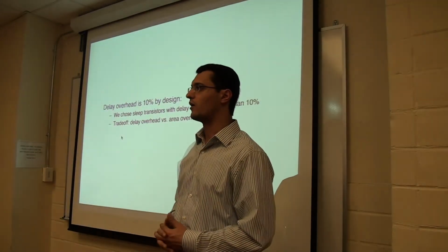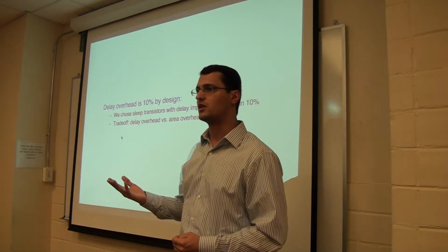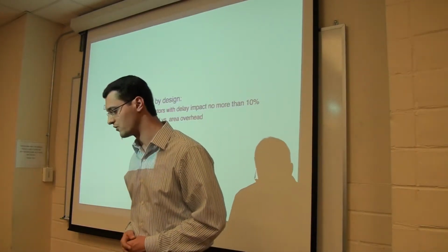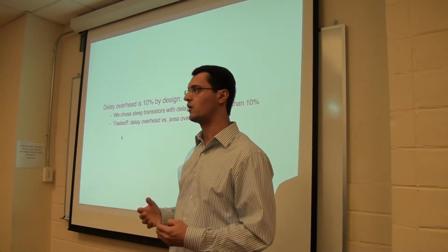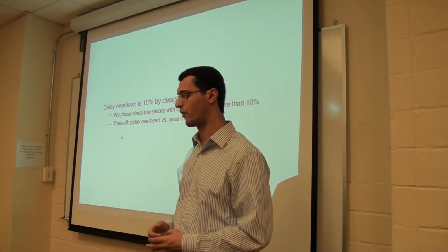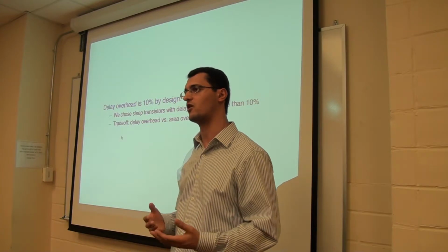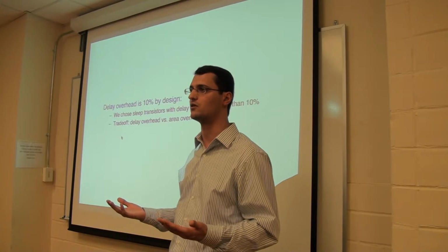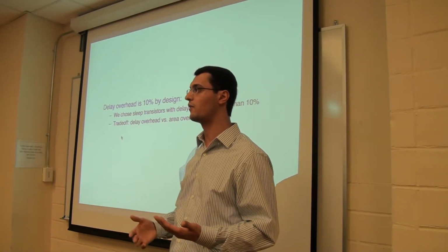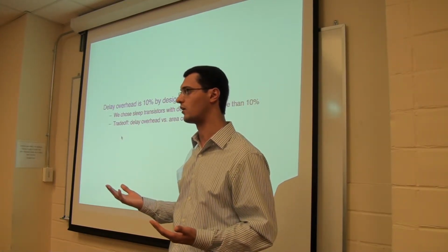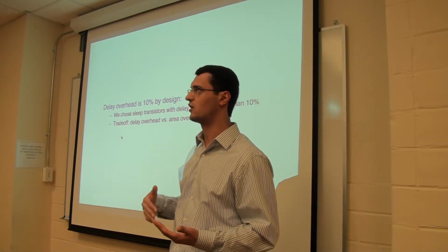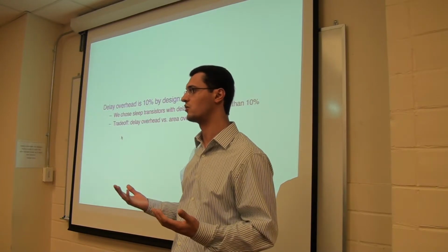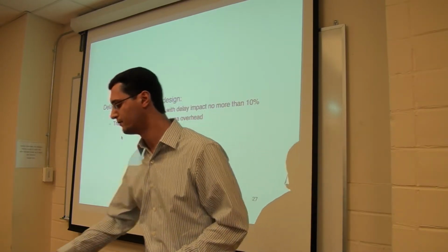So the delay overhead that results from inserting sleep transistors is 10% by design, which means that we sized sleep transistors to make sure that the delay overhead is no more than 10%. Of course, there's a trade-off between the delay overhead and the area overhead. We can increase the size of sleep transistors to get less delay overhead at the cost of increasing the area overhead.